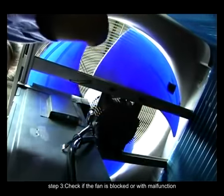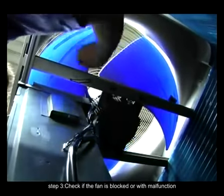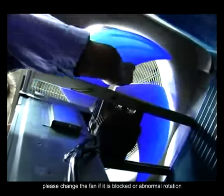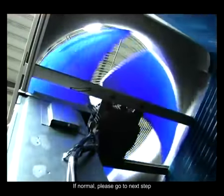Step 3. Check if the fan is blocked or with malfunction. Please change the fan if it is blocked or abnormal rotation. If normal, please go to next step.